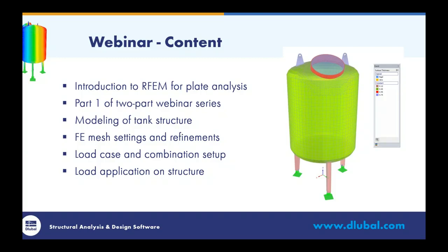We're going to discuss certain aspects such as the FE mesh settings and mesh refinements. We will set up our load cases as well as our load combinations per the ASCE 7. And finally, we will apply the loads to the structure. We won't necessarily be getting into any of the analysis and the design results for our webinar today, but rather that will be covered in the second part of this webinar series.